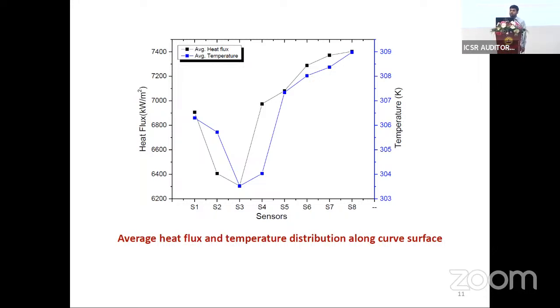So we curve fit. Actually, we discretize that equation by using cubic spline method, and then we estimated heat flux from measured transient temperature from fabricated coaxial thermocouple. It's inverse interpretation.